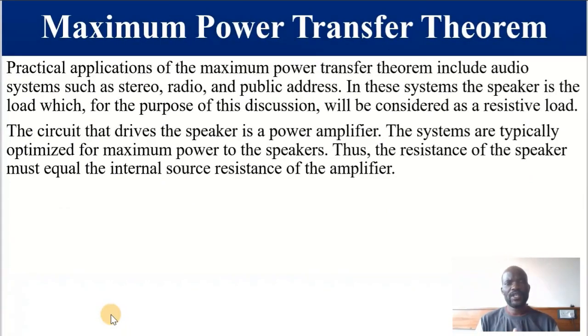We are now going to look at one special application of the maximum power transfer theorem, and this is in audio applications like stereo, radio, or even public address systems. In these systems, we have a speaker of 4 ohms, 8 ohms, or 16 ohms, and that will be our load. For the sake of our discussion, we assume the load has a resistance. So the resistance can be 4 ohms, 8 ohms, or 16 ohms.